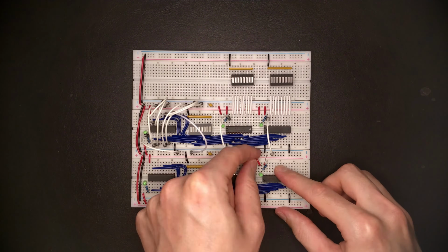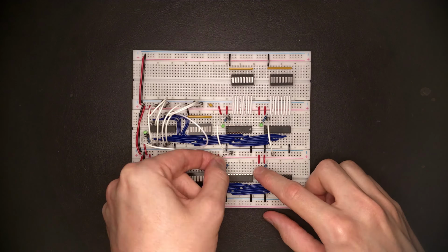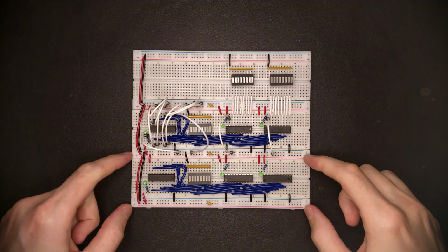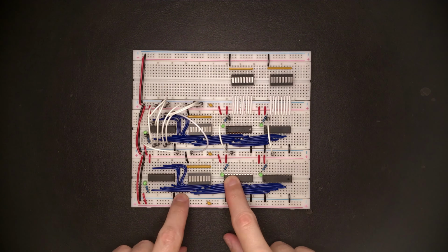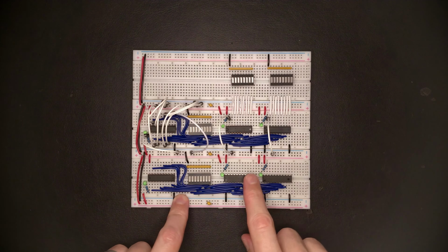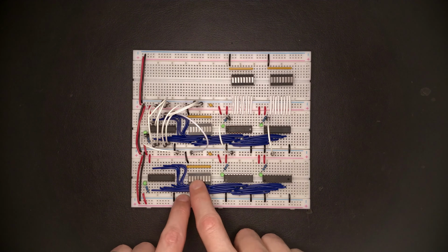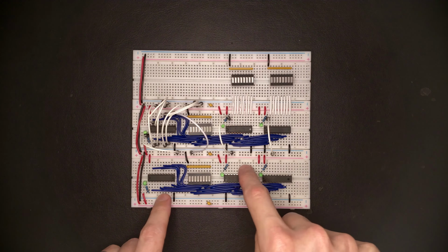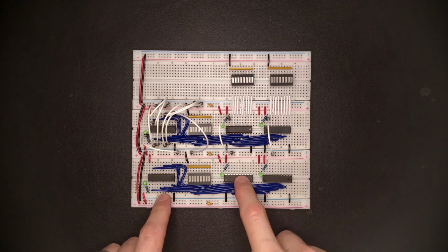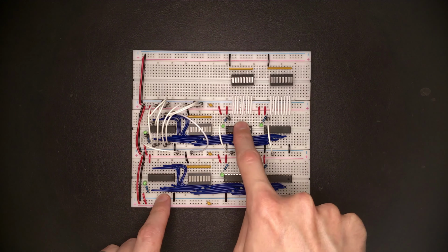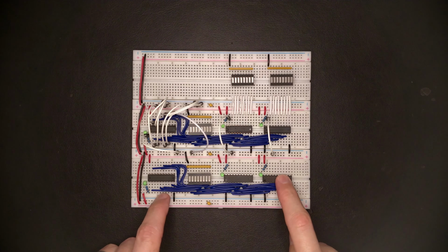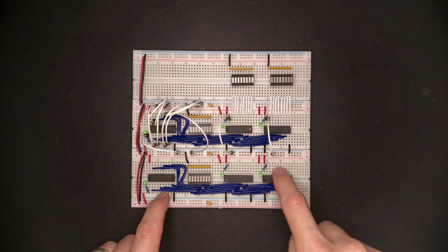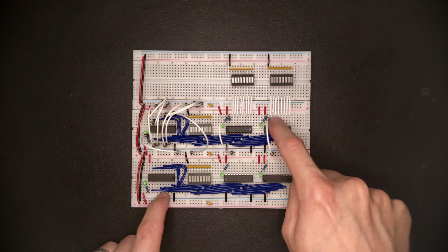Okay, I think that's all the power connections re-established. Now this second register here has its own set of driver chips here that can actually put the value of the register itself onto the read data buses. So what we need to do is actually connect the outputs of this buffer here to the outputs already up here, and the same over here for the second read data bus. We connect the outputs of this register up to the upper one.